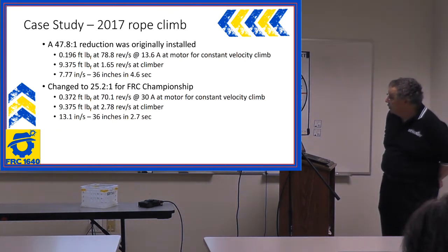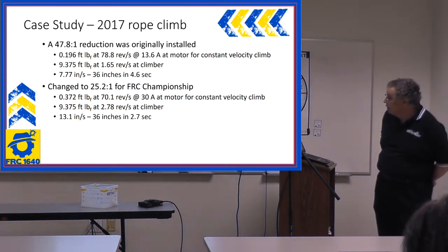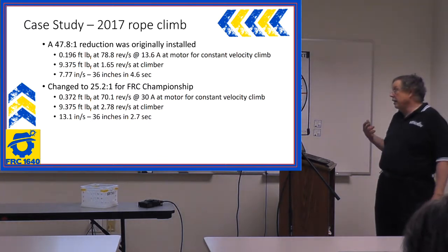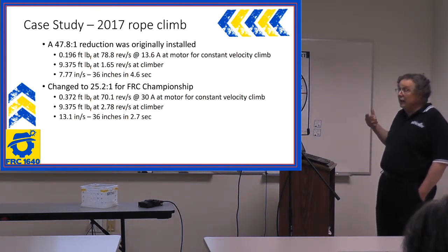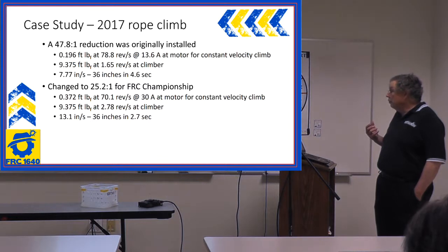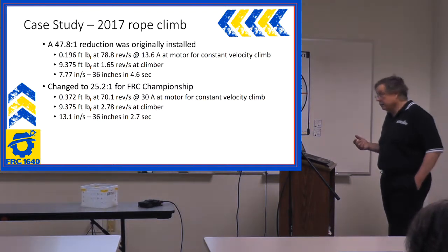When we changed that to the gearing, the 25.2-to-1, we increased that speed to 13.1 inches per second, getting the climb time down to a bit under 3 seconds for just the actual climbing. But we also were pulling 30 amps at that higher speed.